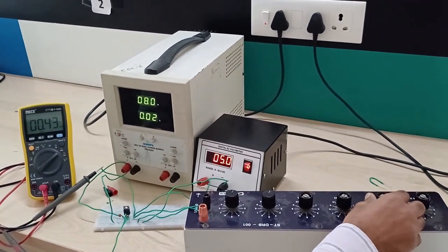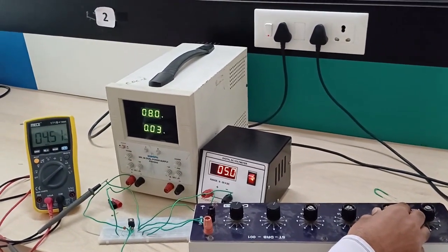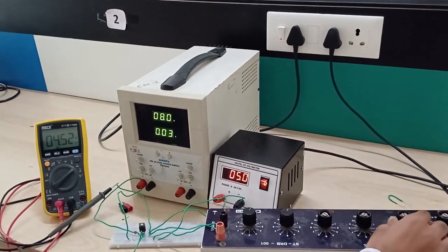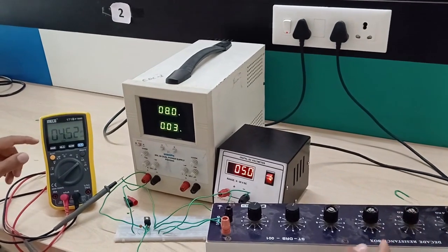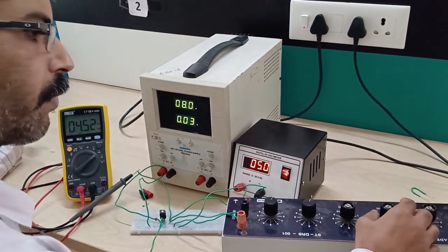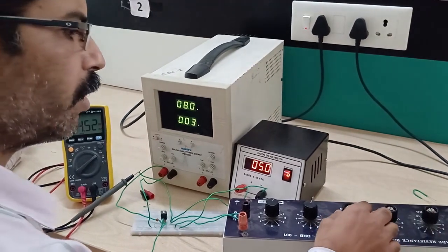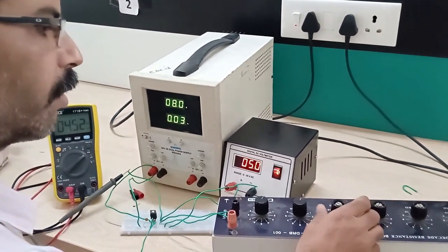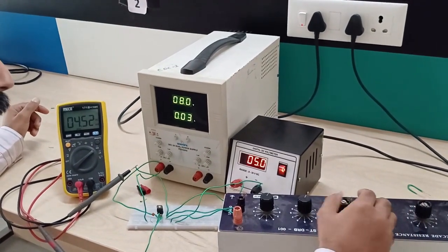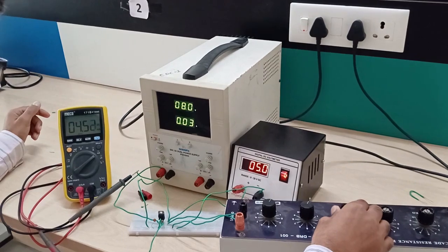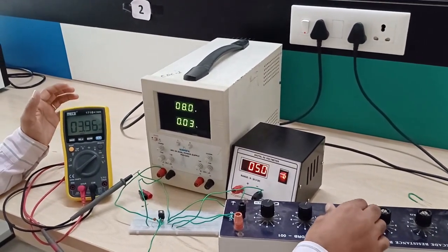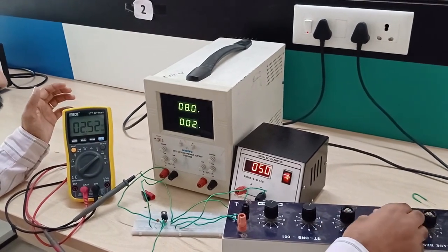So from 10 kilo ohms, I am decreasing. Now I decreased the output load resistance, so I am getting increased output current. Okay. Now it is 1 kilo ohm plus, 1.1 kilo ohms of resistance is there in the output. I am going to reduce this by 100 ohms. The output current varies. Now I am going to keep 1K.